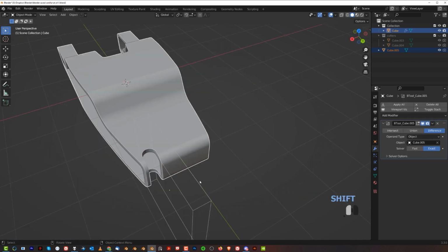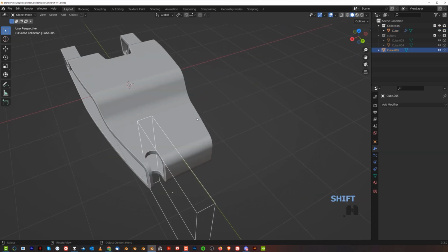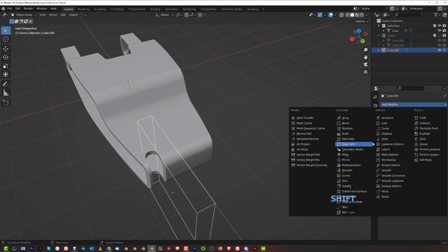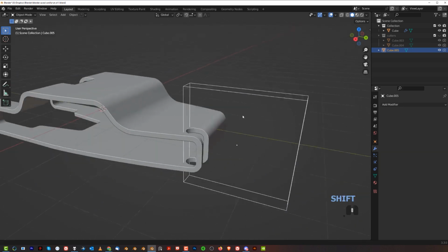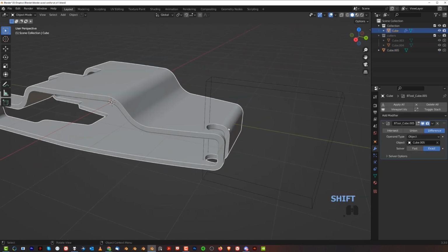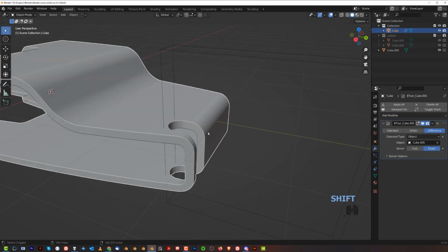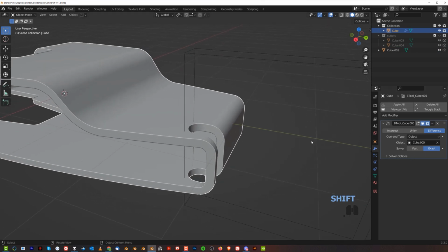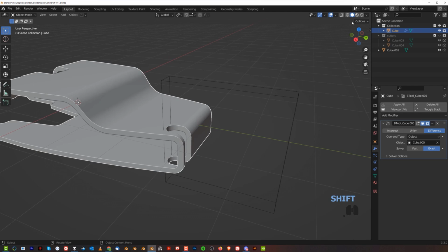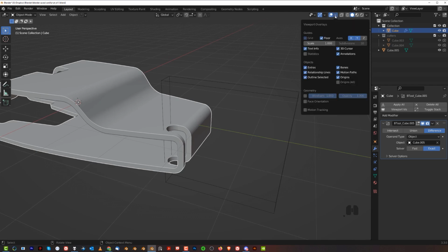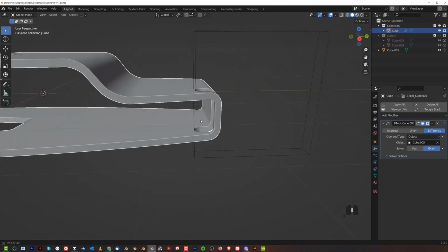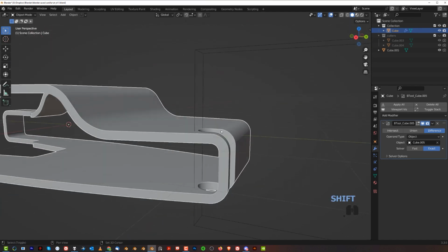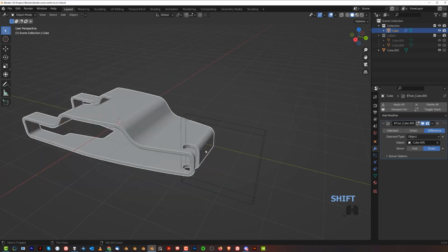And now instead of mirroring the shape, we can mirror the cutter. So I'll show you how to do it. You can go here to mirror. Now you can see that our shape will disappear. And the most likely reason for that is that this cutter is set to exact. Now exact cutters will not work if there's any problem with geometry. Let's go here to this tab and enable face orientation. Everything seems fine, but for some reason when I'm enabling the mirror, the main shape disappears.